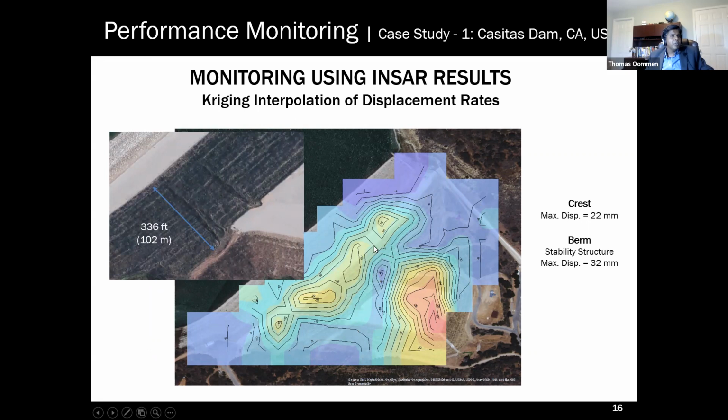Or even if you had somewhere here, you would not have thought that this is as serious as these displacements that you would see. So in the case of the traditional approach, the location where we measure is very critical, and often it is a hit or miss by placing those instrumentation. Whereas with remote sensing data analysis, you have a much higher spatial resolution, and that way you can actually resolve what is happening at your site in a better manner than the traditional approach.